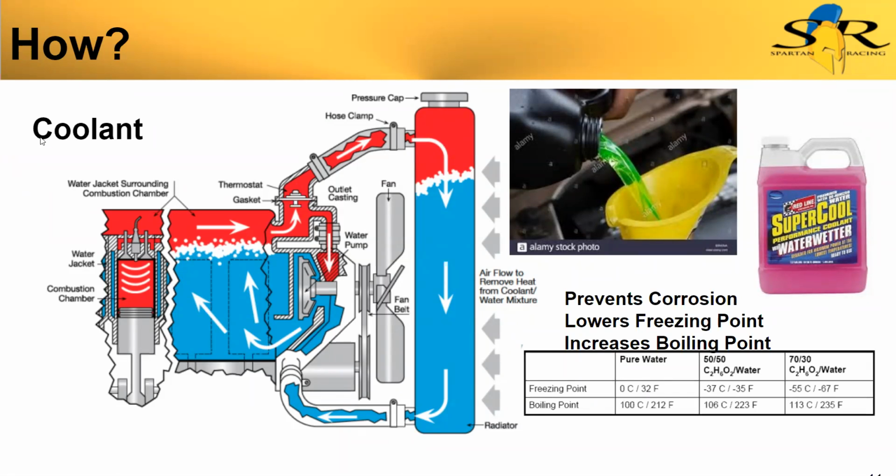So really good point. All that said, we don't get to use any of that stuff because for Formula and combustion anyway, we're only allowed to run water for cooling. So no additives allowed, which is fine because water's all right and it's clean and it's easy and it does a pretty good job.